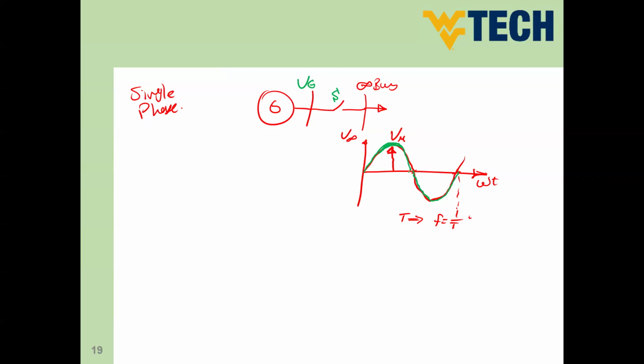How can we do that? Or before that, let's say, what is the measurable value that we can say we can achieve the synchronization? So the measurable values from the waveform here, guys, in order to have two identical waveforms, okay, and matching together from the beginning to the end, firstly, we can say that both waveforms have to have the same RMS value of volt. So same V RMS.